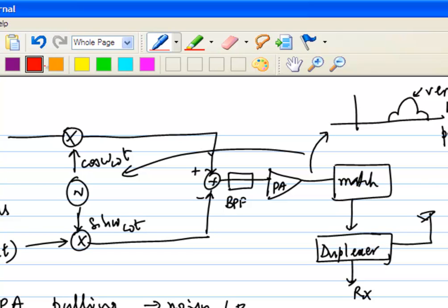This is the LO frequency, right? Typically, this will be several hundred millivolts. We looked at cases where there may be an active mixer. Remember, we talked about how you want to size it. At the end of the day, this is going to have a fixed amplitude, irrespective of whether you generate it as omega 1 plus omega 2 or otherwise. Typically, the VCOs which you design will also have a fixed amplitude. To minimize noise, you tend to have maximum amplitude coming out of the VCO. So the amplitude itself will not matter too much. As long as the frequencies are offset far enough, it won't pull anymore. Okay?